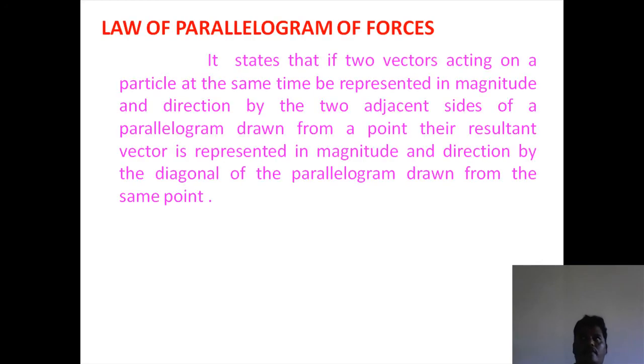First, the parallelogram law of forces. It states that if two forces, otherwise two vectors, acting on a particle at the same time, represented in magnitude and direction by the two adjacent sides of a parallelogram drawn from a point, the resultant vector is represented in magnitude and direction by the diagonal of the parallelogram drawn from the same point.